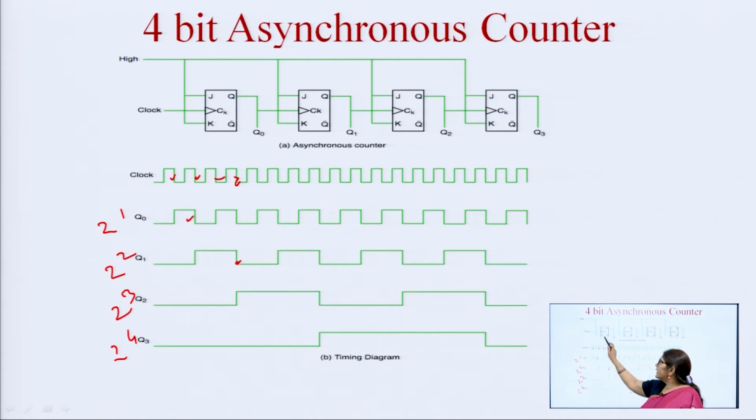Again, when the first clock pulse appears, it will change from 0 to 1, and because this is a positive change, it will not affect the second flip flop.